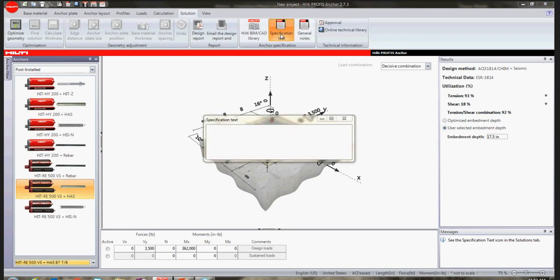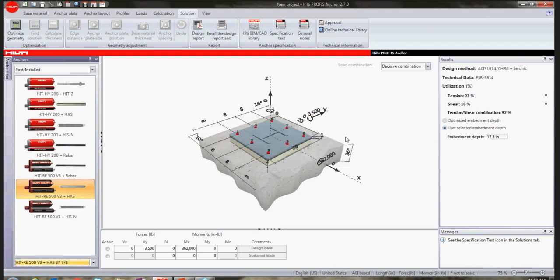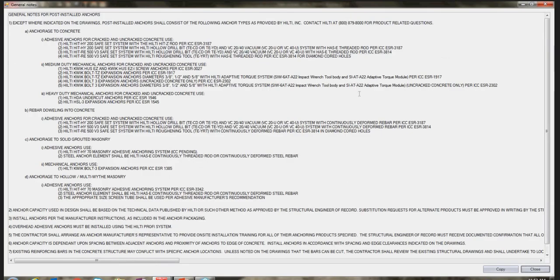And then we have provision C, which is going to be this crushing of the fixture, so a brittle fixture failure mode. And then option D is going to assume all of our failure modes will be brittle, and because they are brittle, we're going to apply an omega naught overstrength factor to the earthquake components of that factored load that we've